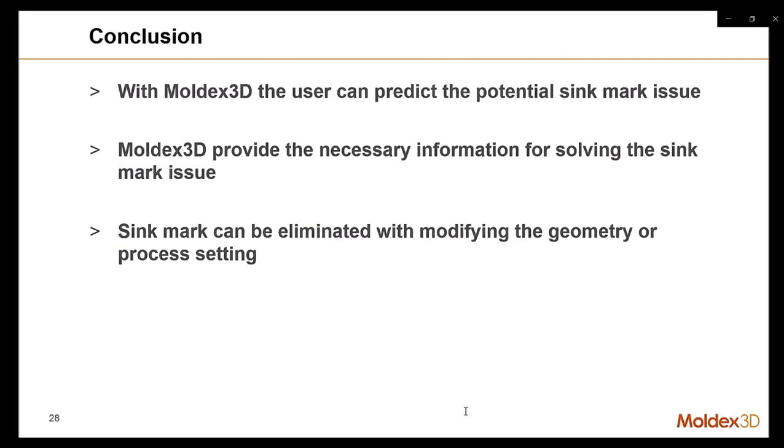It can really save your time and money. You don't need to do the tooling update before you get a great prediction. And we also showed you several examples of how we deal with seam mark. We did the geometry update, and we also did the process update. So by using this kind of update in the environment of Moldex3D, we can really help you to predict seam mark.